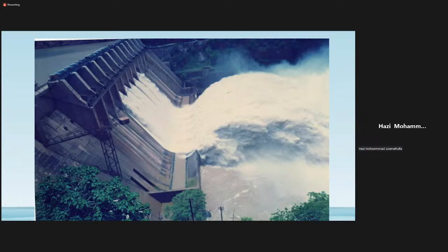So that's why, if they have the lip angle very far, but what my boss was telling at that time, if 35 degrees, some even 45, how will it work? But all model studies, 1 is to 42, 1 is to 70, give good results. That's what they proved, even European hydraulicians. So here the problem is 30 degrees, so your jet is coming very near to the structure, the main structure lip, then immediately not going further, even though there is so much energy. Energy means, you are all aware, right? Energy equation, velocity head, pressure head. Next please.